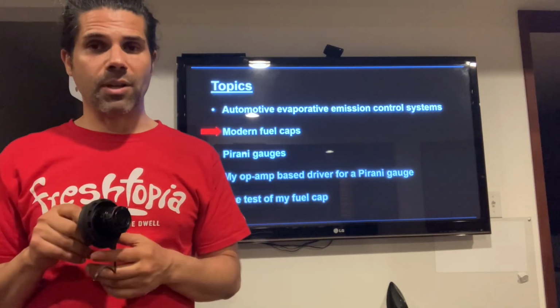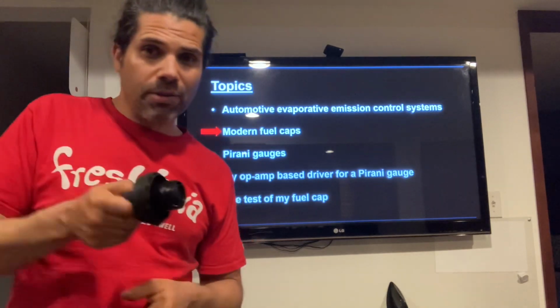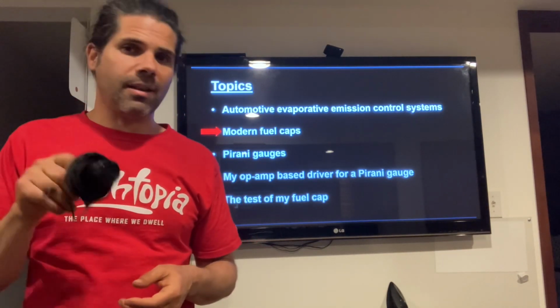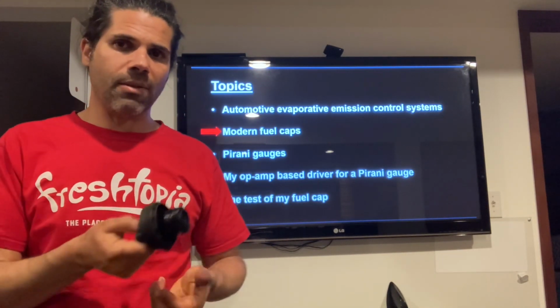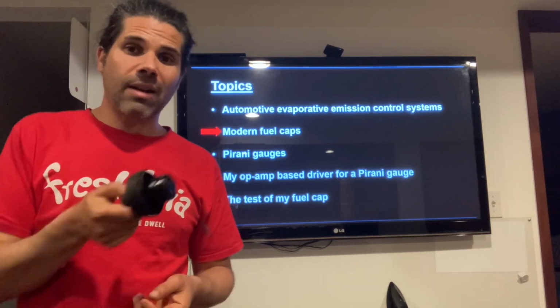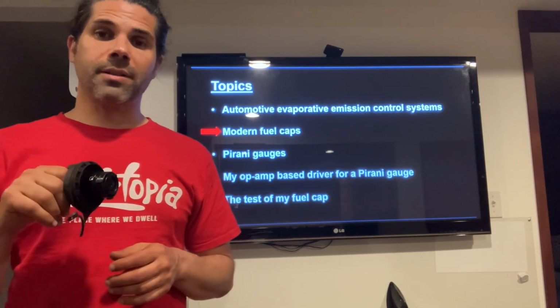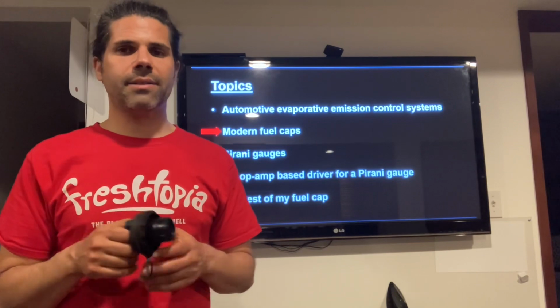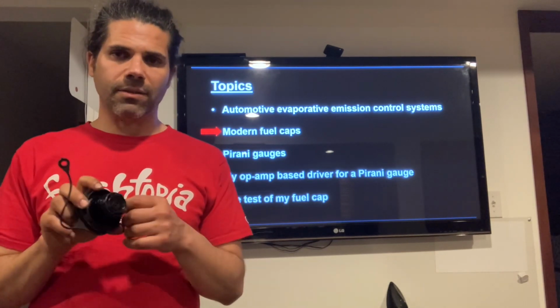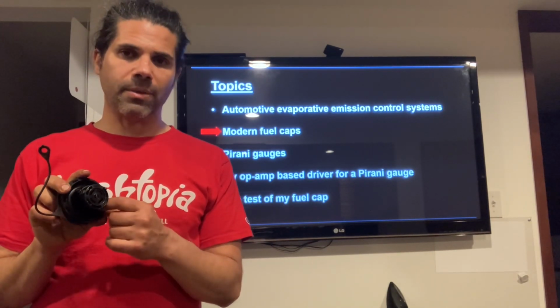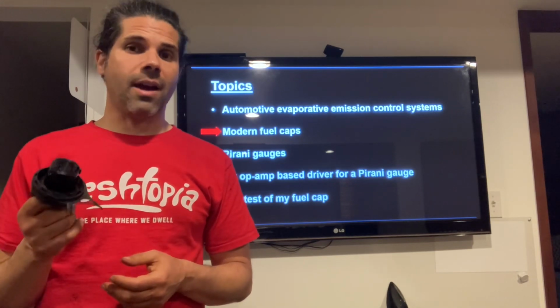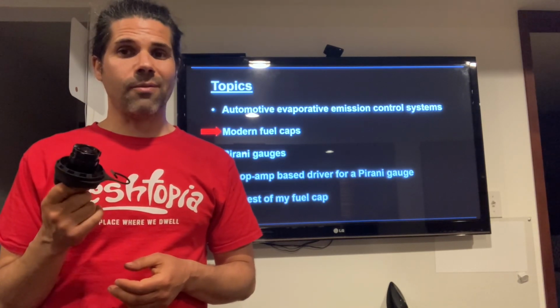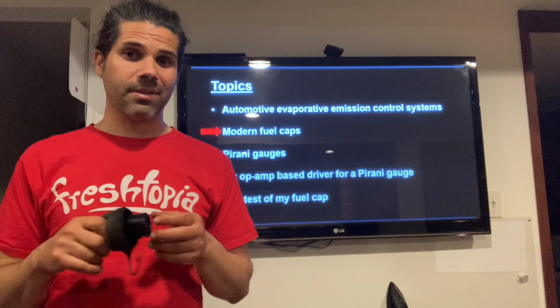Your car will give the check engine light. Make sure it's in well. Sometimes you're in a hurry, whatever, it's not all the way installed. A lot of them have a click that they are tightened enough, but not too tight. So you can get that seal of the fuel port rim against the O-ring. So the other thing to check, and this one is not so straightforward, is that it actually seals.